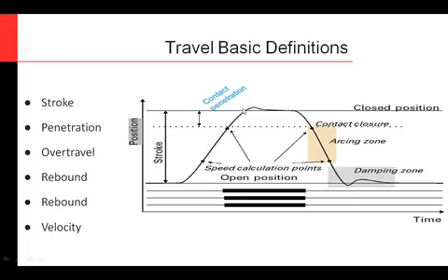And so usually the manufacturers will give some kind of parameter that you have a maximum over travel of 5 millimeters or so, because if it's going too far, you might be doing extra damage to the interrupter and slowly busting it apart. Rebound. This is something you'll have when, say if you over travel and you come back, you'll notice on the close operation there's no rebound. It just over travels, dampens out, and is fine. Now as we come back and we do the open operation, we're coming down through here, we have an over travel, and then it comes back and rebounds in here, and then finally comes to resting position.